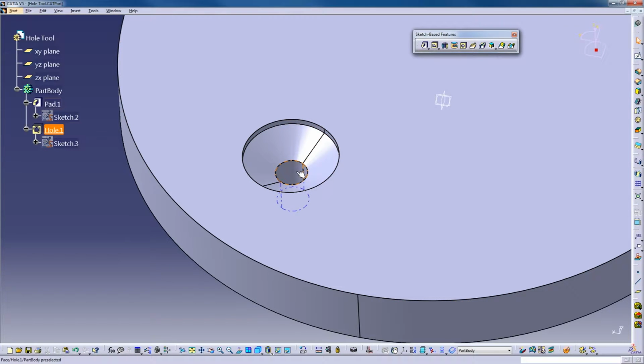I make the spiral, but it's just a thread. Then I have to stick a triangle or something like that on that line, and what I end up doing is, if you remember the rib tool, I'll take that triangle and have it follow the helix down, and then I'll get my thread. But what pitch do I make the helix at? Well, I've got to bring up the data sheets for actual thread. So then all of a sudden I leave being a designer.